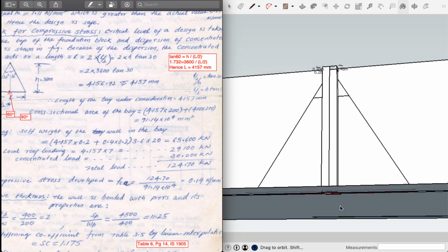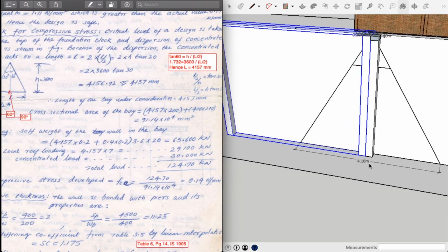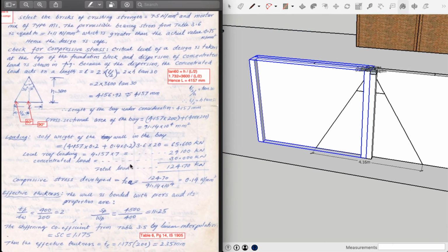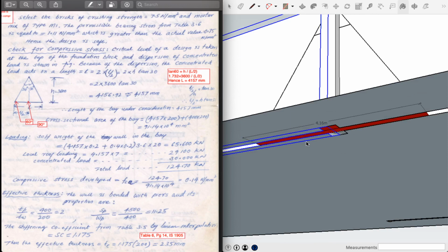Moving on, now that we calculated the area on which the load is being acted, we need to calculate the total amount of load that is actually happening. In order to do that, we're first calculating the self weight. In order to get the self weight, we multiply volume by its unit weight or density. The volume over here is 3.6 meter, which is the height, multiplied by that cross sectional area. We get the volume of this particular span.